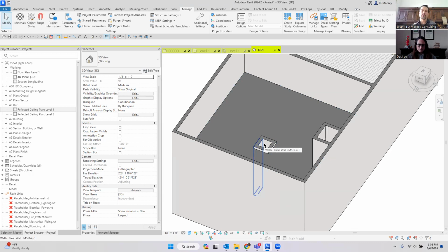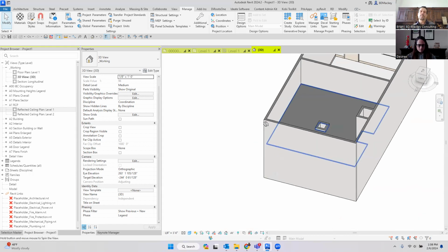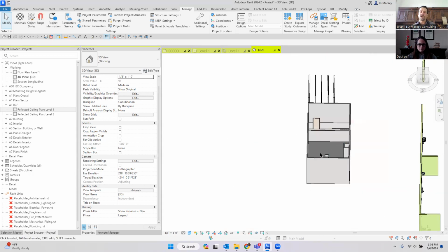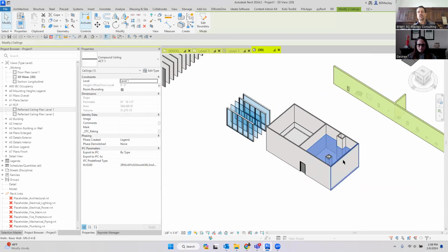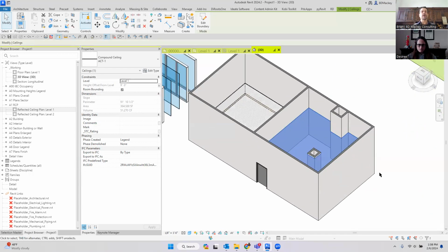So it is kind of one of those tools that I've been using with a client where we're modeling some existing structure. And like I said, there's like 32 offices the same. There's all these different walls, even soffit walls that are coming in. Coming inside of there and saying, cool, we've got to do that. So we've been using those global parameters. And we've got one for level 1 and we've got one for level 2 in the event those change. So currently both ceiling heights are typical 11 feet for both floors, but we said level 1 ceiling height typical and level 2 ceiling height typical.